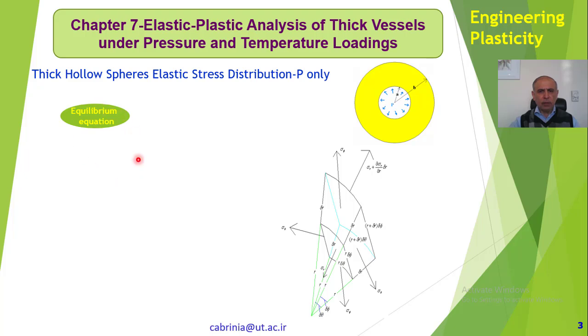So first of all, in this kind of problems, we must write our fundamental equations. One of the fundamental equations is the equilibrium equation, because as you can see, we have this internal pressure here, but nothing is happening. It's static. So we must have equilibrium equation. We must have equilibrium. So we derive the equilibrium equation.